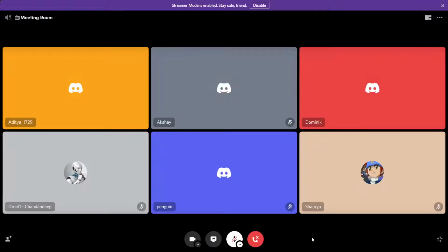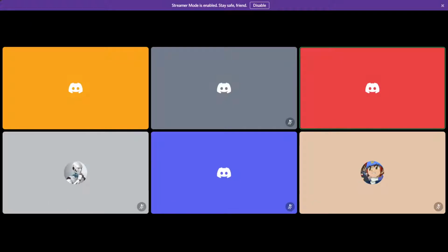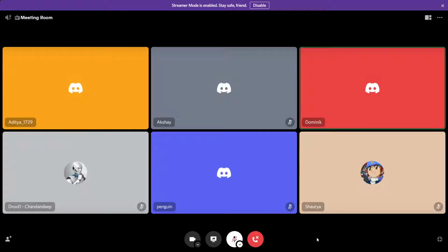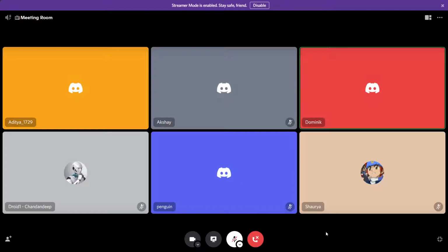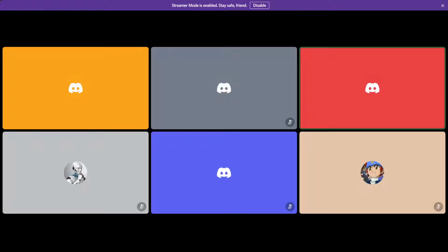And then in terms of observations, the robot knows whether either one of the fingers is in contact or not, and it knows the pose of the object, and we encode the distance of those fingers to the individual contact points. As actions, it can contract the tendons to create motions. Then we use the Stable Baselines PPO implementation, just to see what it can learn with that information.